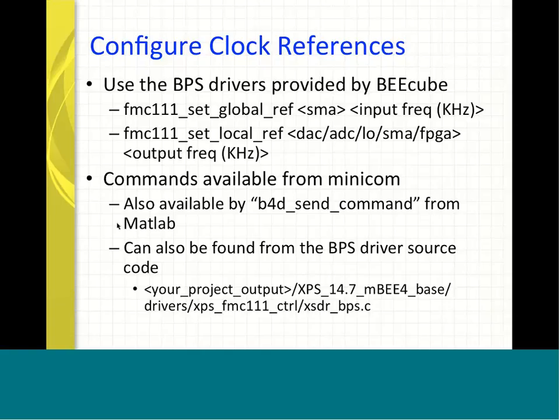That limitation actually comes from the FMC111 interface IP, not necessarily from this chip. So this chip can give you a lot more flexibility. However, to simplify the design, we choose those frequencies to simplify the interface between the FPGA and the DAC or the ADC.